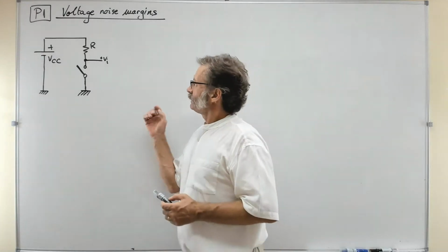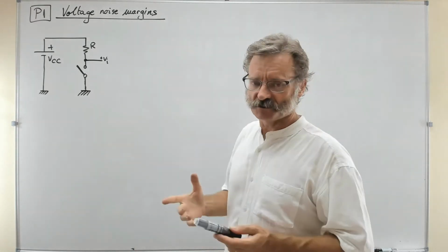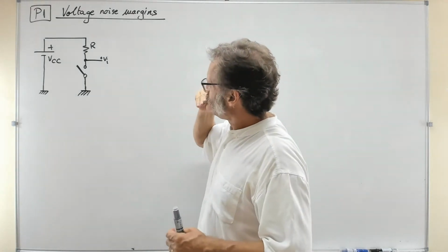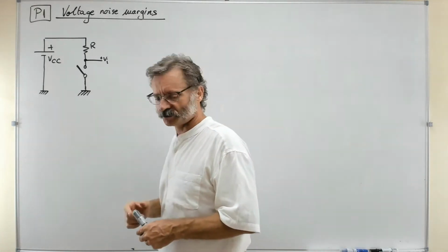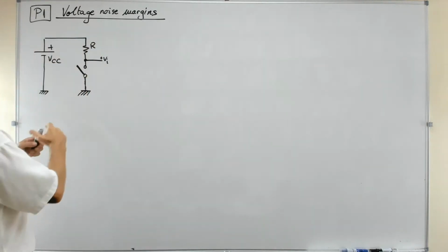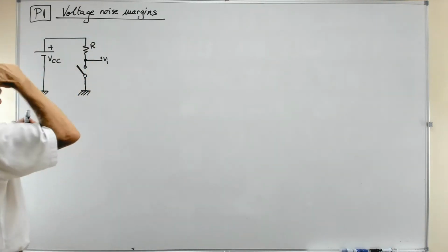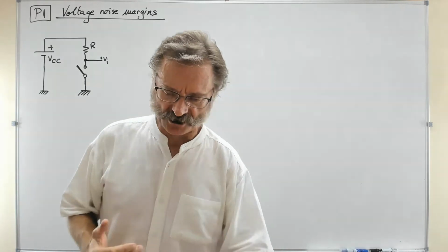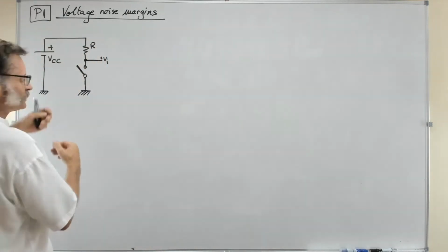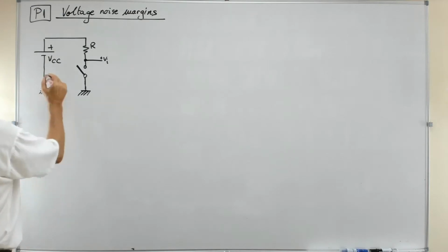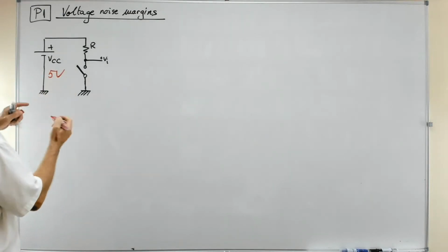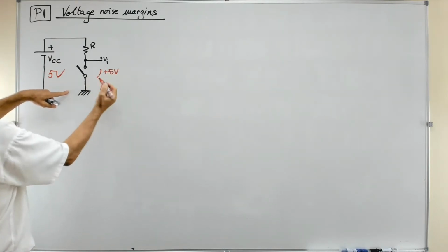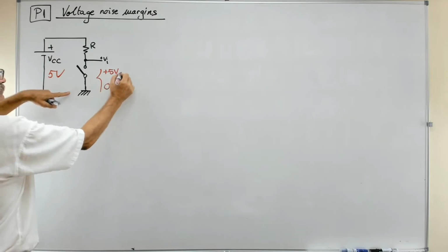So let's just start now this recording on another concept which is quite important and is maybe the continuation of what we had here previously on the idea of a switch or a push button and the gate. So you see, this is the circuit where you are generating a clear 1 and a clear 0, but indeed what you are generating here is a clear 5 volts or VCC volts and a clear 0. You see, if this is 5 volts, you are generating here the VI, which is plus 5 now, or 0 volts. That is the point.